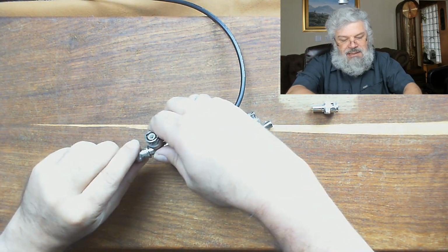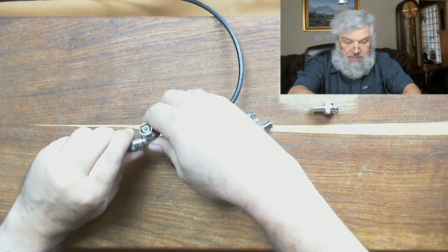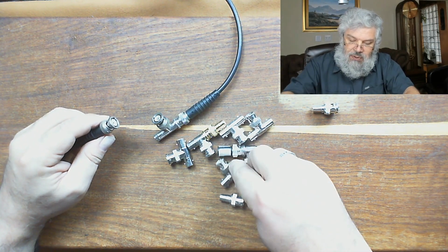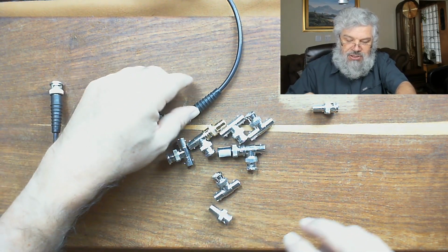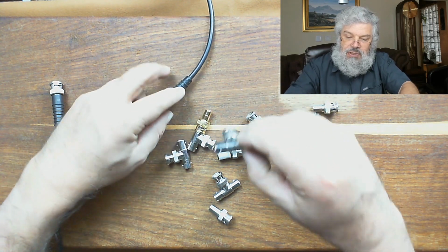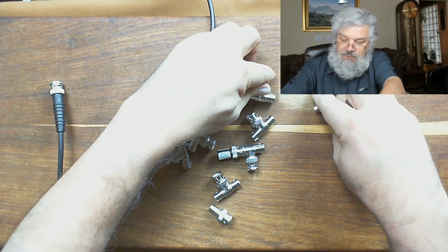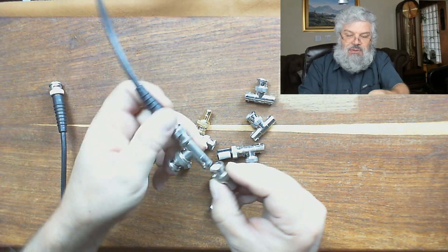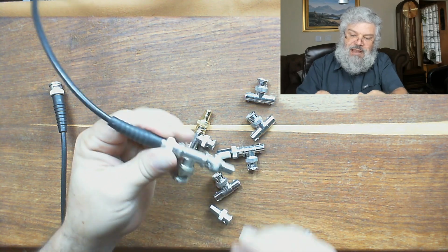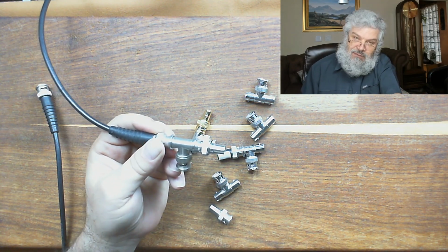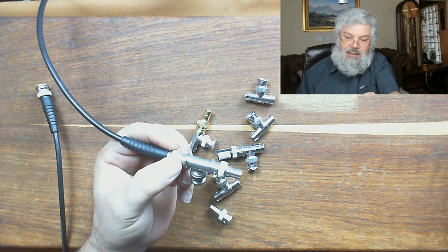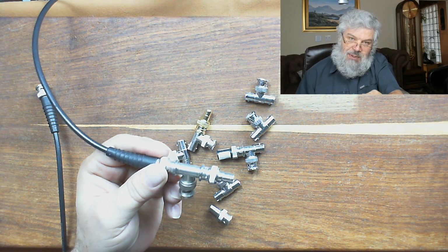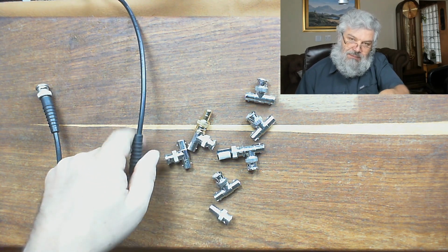One interesting thing, if you ever encounter this, because this has also become really, really scarce and it doesn't work, then chances are that you don't have the 50 ohm end connector in place. So at the end of every cable, it needs to be terminated with that 50 ohm. I think years have been lost because many people didn't know about that requirement.